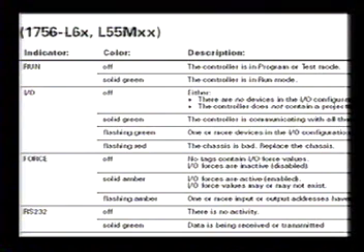Now, when you get a brand new processor and you drop it in this rack, you're going to find out that that thing is flashing, right? And you're going to say, hey, what's going on there? Really, it has no firmware. So you want to go ahead and upload the firmware first. After you've uploaded all the firmware, then you won't have this flashing light. And I've actually run into a problem where I did have a bad chassis, and it gave me the same indicator as bad firmware.